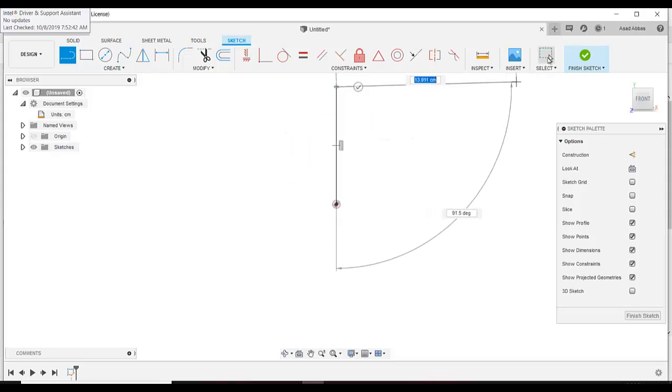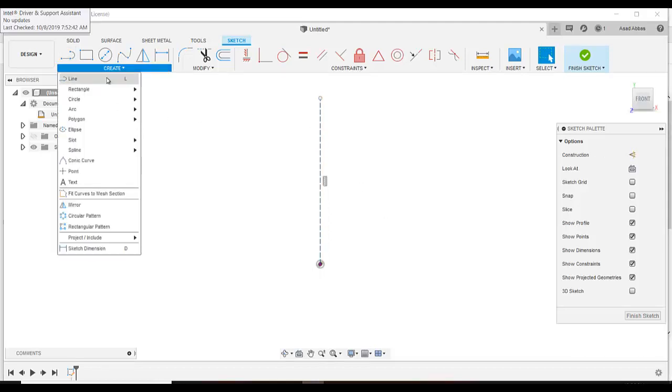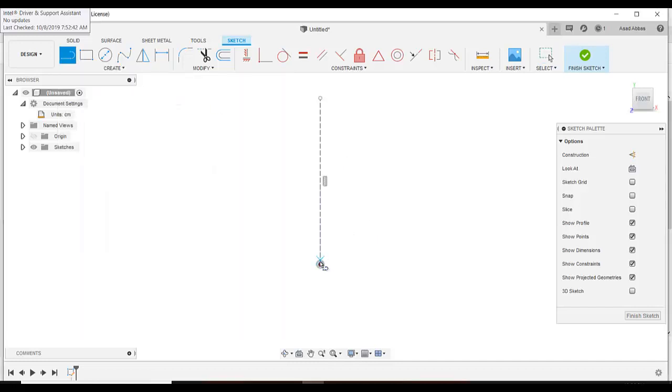and then click next. So this is the line I just drew, but I want to make this line a construction line. I made it a construction line. For the construction line, we just want it as a reference line, and draw a horizontal line. This line we also need for our reference. So select it and then click on construction. Now we added two lines, a vertical line and a horizontal line, but these two lines are just for reference in the sketch. And then go to line.